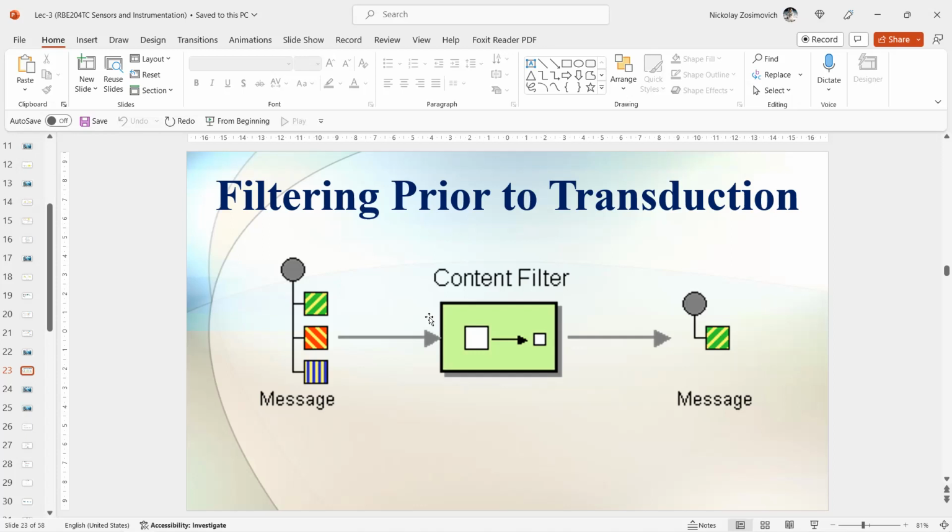First of all, there is electric injection of a spurious signal through a capacitive connection between the error voltage source and the system input, to be avoided by a grounded shield around the sensor structure and the input lead. The capacitively induced current flows directly to ground and does not reach the input of the sensor.